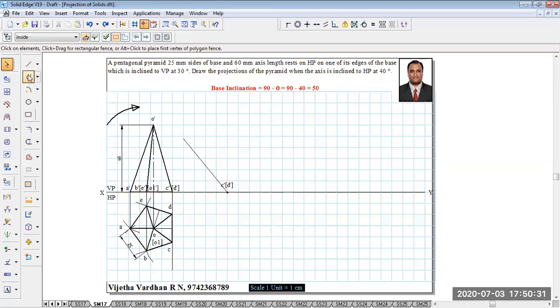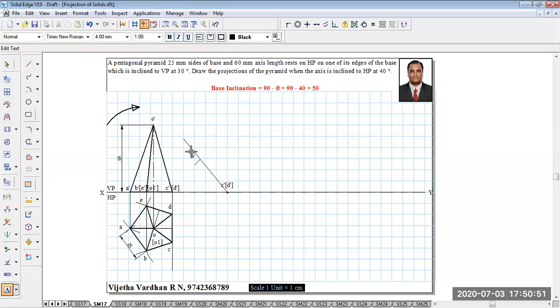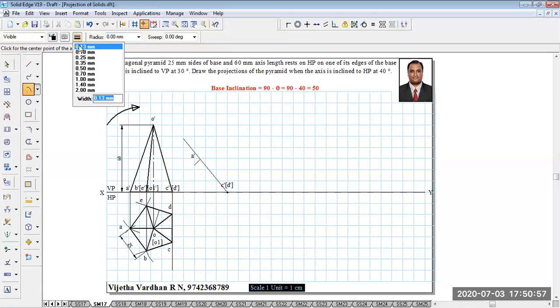Keeping that in mind, you are not supposed to show the dimension. And then, to get the front view as it is, using the arc technique, what one has to do is use the compass and measure C dash to A dash, with C dash as the center. Now you obtain A dash on the 50 degree line over here. Now this corner is going to be marked as A dash. In the same fashion, to obtain O dash, using the arc technique, the same procedure: measure C dash to O dash with C dash as the center, without changing the radius, and draw a constructional arc like this.